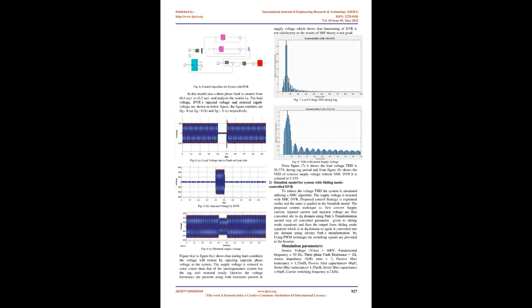The simulation study gives a comparative study of the system without sliding mode DVR, the system with sliding mode controlled DVR, and terminal sliding mode controlled DVR. The comparative analysis is done by observing the reduction of supply voltage harmonics and voltage sag restoration ability.